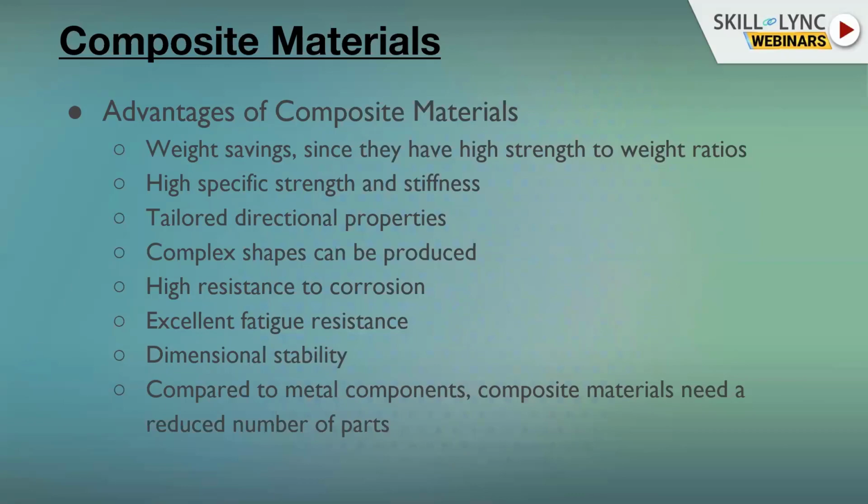What this means is the parts that are produced with aluminum or steel have a very high coefficient of thermal expansion compared to the parts produced from carbon fiber or glass fiber. So the parts have good dimensional stability, and with rise or reduction in temperature, the dimension of the part is quite stable. It doesn't vary a lot when compared to aluminum or steel.